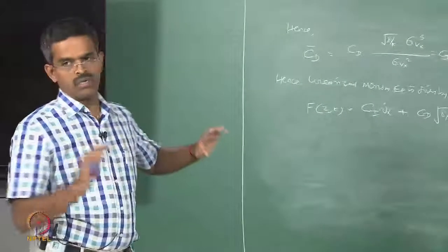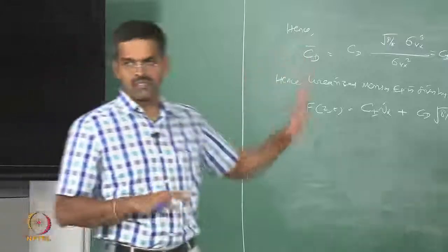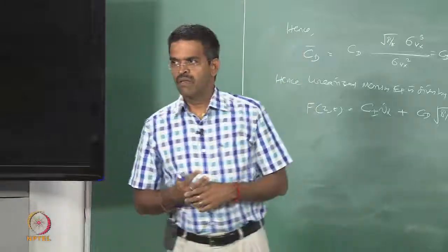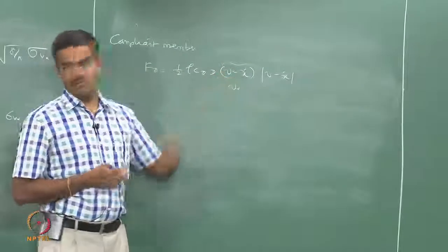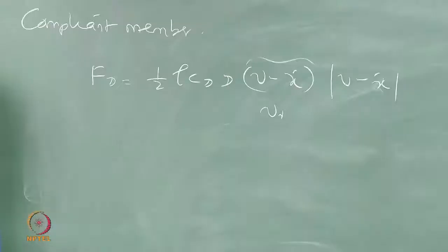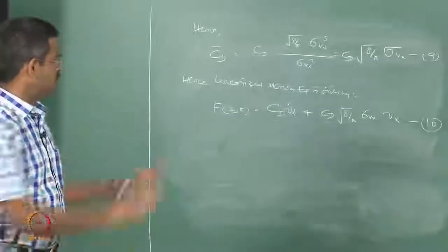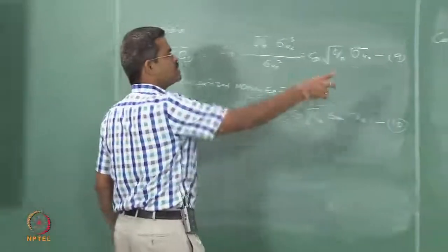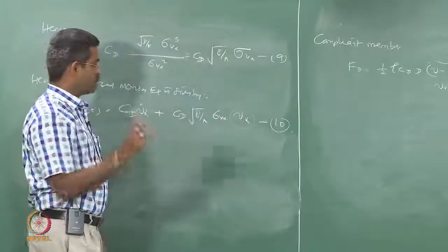Because the equation of motion has got the displacement as the solution, therefore velocity and acceleration are not known to me. So, initially you cannot evaluate this term unless you assume this and keep on iterating. When you have got a nonlinear term, it is very difficult to iterate. So, I want to linearize this. Compared to this power of 2, I have got 1.596 as we pointed out in the previous minutes for example.